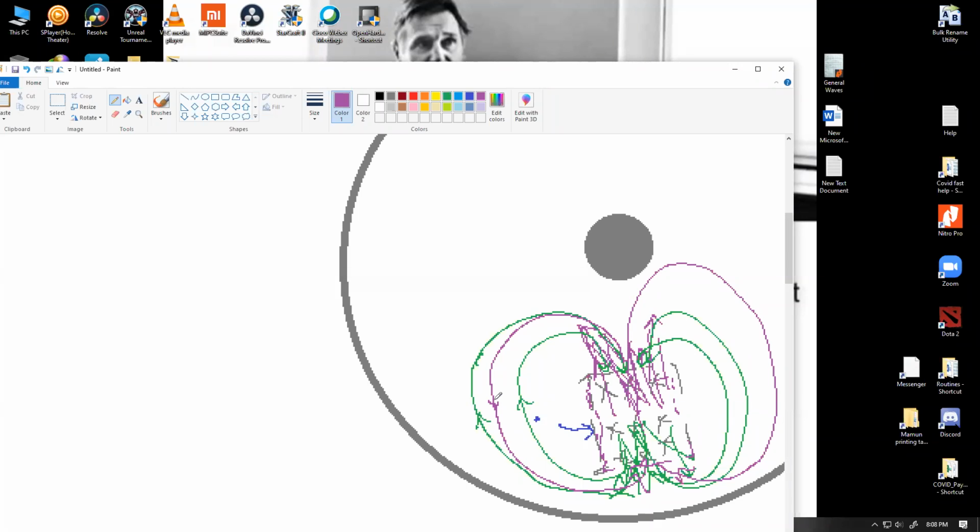Because all the parts are not affected by the same amount of magnetic field, we have affected only a small part of the disk with a magnetic field. That's why we are going to have this flow of electrons moving through the plate itself. As these electrons move through the lattice of the metal, traveling from the lower side of this rectangular part all the way to the top side, they are going to collide with the fixed ions of the metal piece. That will develop resistance, and that will give you an extreme amount of heating. We are talking about moving millions, if not billions, of electrons. So all the individual electrons will produce some significant amount of heat energy.